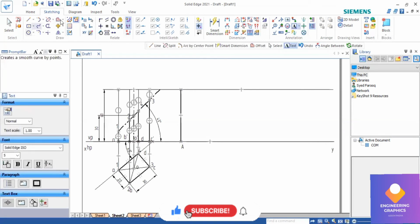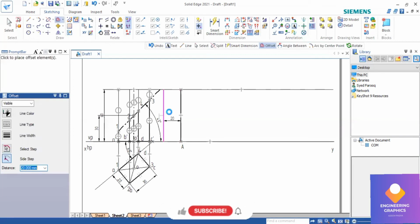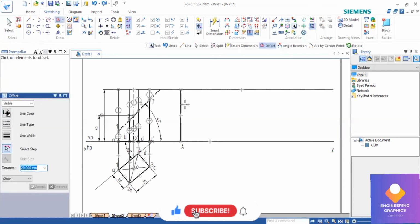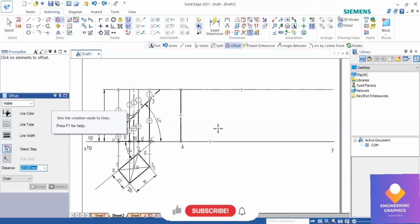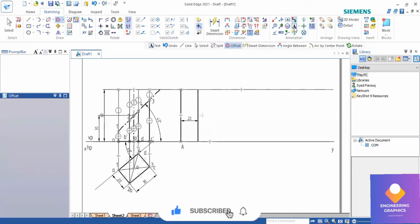From A to B, you can see it is 20 mm. So I'll be using the offset command. I'll be giving the distance of 20, enter. So you have to take it on the forward side. You have to make sure here, you may be getting it on either side. You have to make sure you get it on the forward side. Okay, next from that is your point B, capital B.